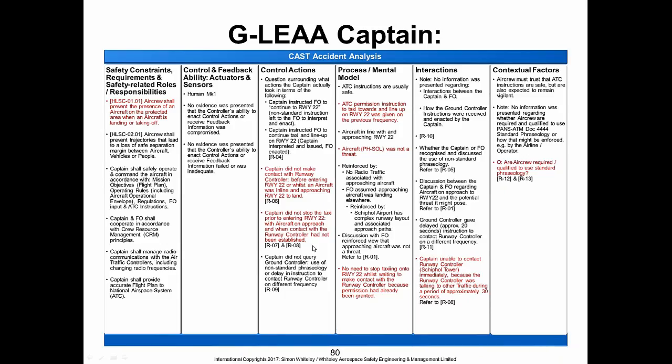And then the captain did not stop the taxi prior to entering runway 22 with an aircraft on approach and when the contact with the runway controller had not been established. And also the captain did not query the ground controller's use of non-standard phraseology or the delay in instruction to contact the runway controller on a different frequency. Now that generates a requirement which is related to this contextual factor over here.